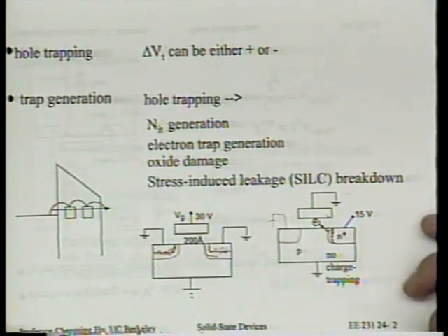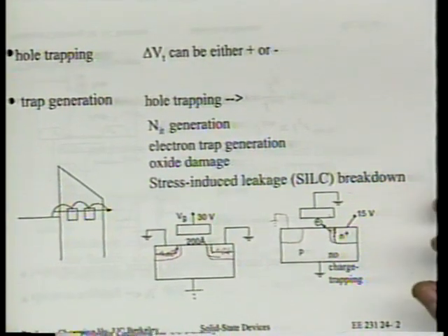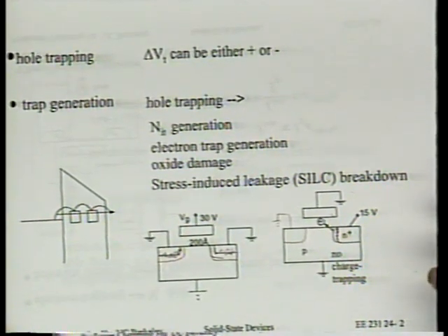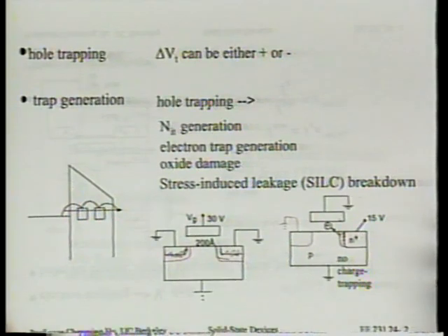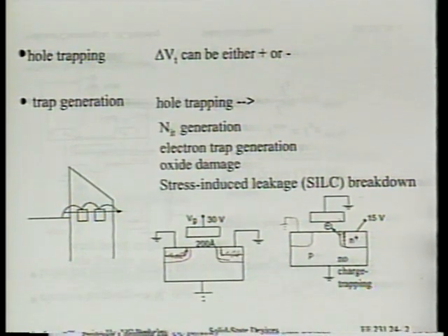So you ask, who wants to break down an oxide? Well, it turns out breaking down oxide is an interesting way to make a programmable device. You can have two lines that are separated, insulated from each other by an oxide, right? But if by a short voltage pulse you can break it down and form a short, that's a very useful way to program circuits called FPGA, right?